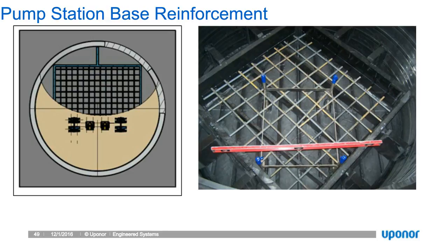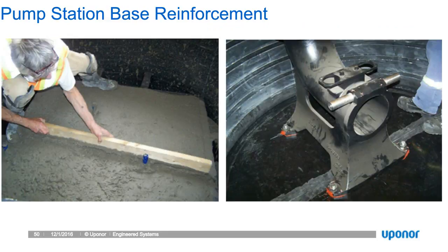And the next slide is just an example of that fabrication with a finished product on the right-hand side with a simplex submersible breakaway fitting that's anchored. As you can see there, the concrete's being cast, the anchor bolts are set into the concrete, and the system is actually fully encapsulated in HDPE. So we still get a 100% HDPE vessel, but we do have that concrete vibratory load resistance cast into the bottom of the structure. And that concrete, in case anybody's wondering, is typically sized to 4 times the pump weight as a standard in accordance with AWWA.